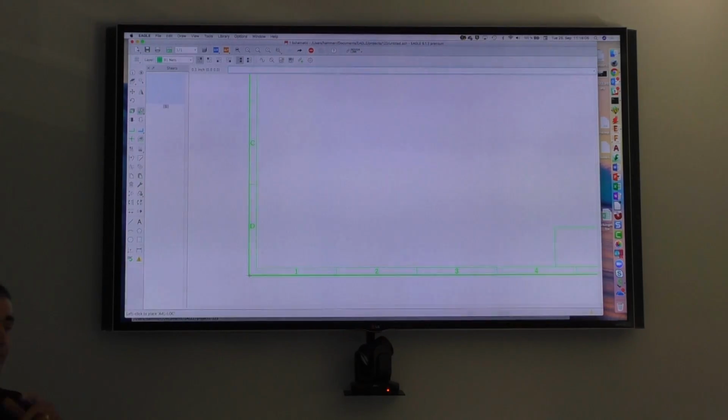Of course, it has nothing to do with functionality, but it's better to have a signal that's named ground or plus 5 volt and not N$12 or something like this. That doesn't help if you search something. Of course, the board works the same as it would be named whatever you want to, but it makes sense to do proper work here. Okay, left click.